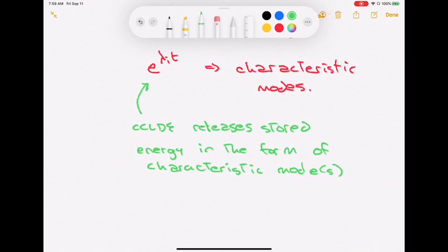We had mentioned back in the background chapter that understanding exponentials was crucial to this class. You have to be able to understand exponentials. This is really our first tangible confirmation that that's the case. When we look at this huge class of systems, which you've studied quite a bit back in circuits, those described by a constant coefficient linear differential equation, we see that the way these systems want to release energy is always in exponential form. Now, the shape of that exponential depends on Q. Different polynomial Qs give you different characteristic roots lambda, and those change how the output can look.